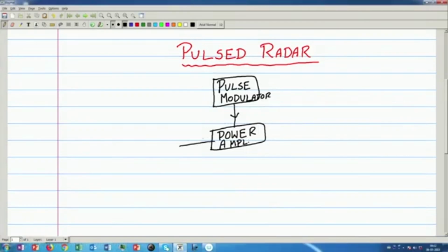then that will be given, but we already know that in pulse radar generally the same antenna is used for transmission and reception. We have discussed that antenna is a costly device at RF level, this high microwave level, and since pulse radar is not always transmitting and when it is not transmitting it is listening, the same antenna can be used. So, for that we need a duplexer and that is connected to the antenna.